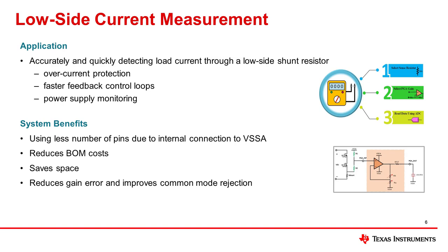The PGA uses only one pin to sense the voltage drop directly across the sense resistor. If a higher level of accuracy is needed, the PGA can deliver it by measuring the voltage across the resistor directly using 2 pins, thus removing any voltage drops from the resistor to the PCB ground.